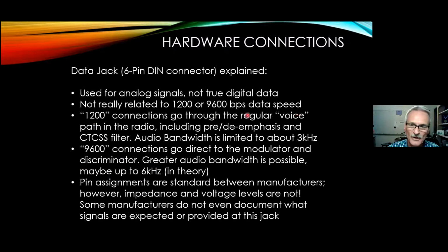This is really important. Kevin and I had a discussion today that a lot of folks really don't understand the pre-emphasis and de-emphasis that happens in a radio. When you're connected to the 1200 pin connections on that connector, or if you're using the microphone audio on your radio, you are going through the regular voice path through the radio, which includes pre-emphasis and de-emphasis, and possibly CTCSS filtering or tone filtering. That's going to limit your audio bandwidth, and that means you're not going to be able to push as much data through that path.